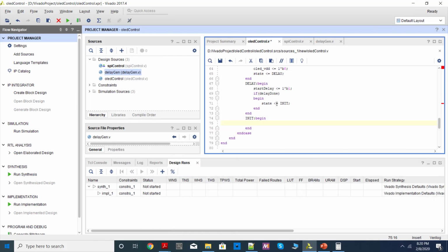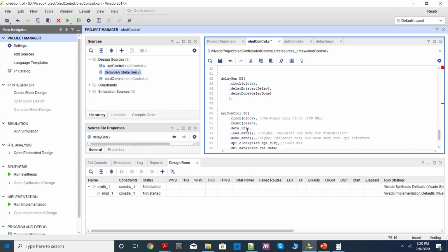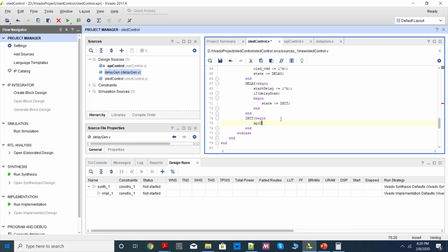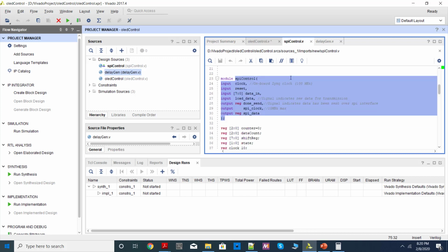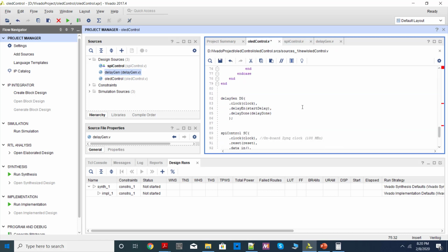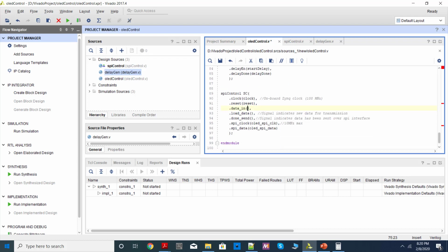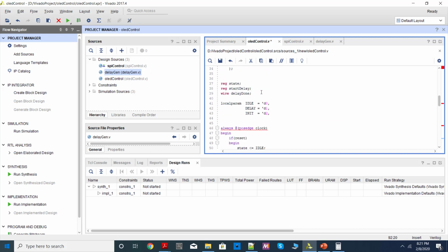So we need to send that command AE through this SPI interface. So what I'm going to write is SPI data is 8'hAE. Now remember how the SPI controller works. He needs to get the data here, and he needs to see this signal going high, then only he will start sending. So that signal is here. We need to connect all the signals here. So SPI data, I'm going to connect to data in, and it should be declared as 8-bit wide, reg [7:0] SPI data. Under reset, initializing data is optional, but it is mandatory to initialize all control signals. But let's initialize to 0 under reset.